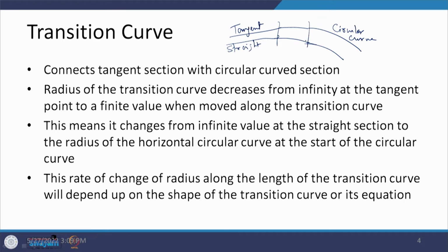Because we are going from a straight section to a circular section, hence the name transition curve. So, it connects the tangent with the circular curved section.